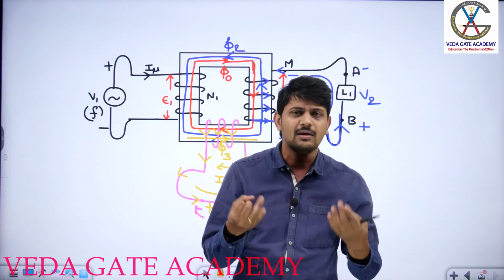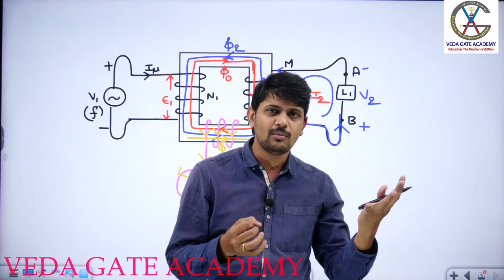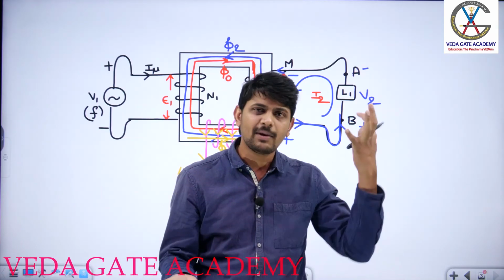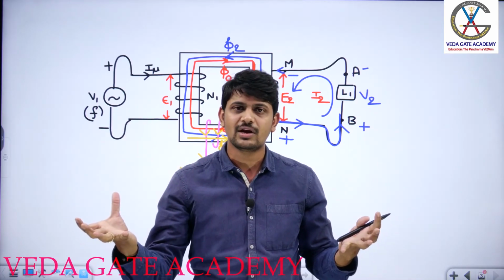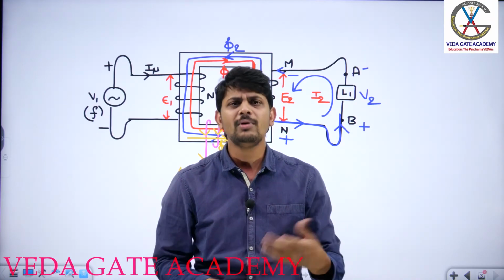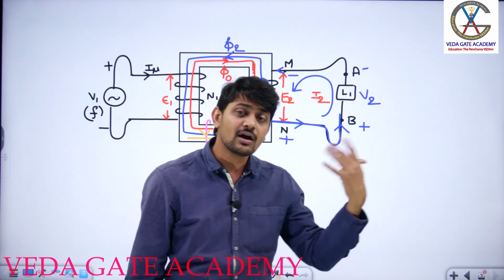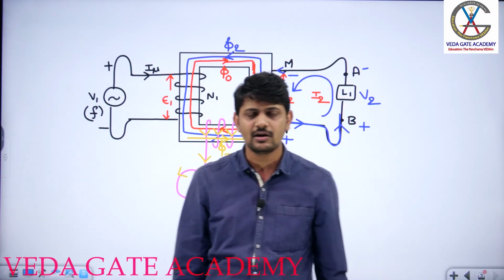There are a few interview questions. Suppose you are taking an electrical machine, what will it do? It will convert either electrical energy into mechanical energy or mechanical energy into electrical energy. But the common medium for the conversion should be a magnetic medium. You may have a doubt that in the interview they will simply ask, why magnetic field? Why can't we use electric field? This is one of the standard interview questions.